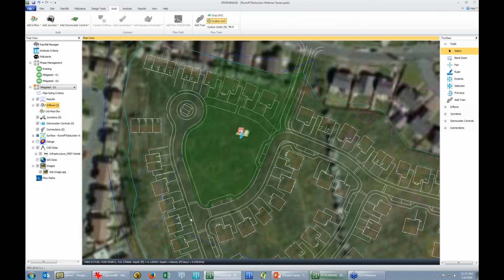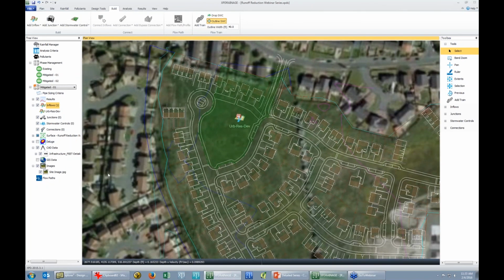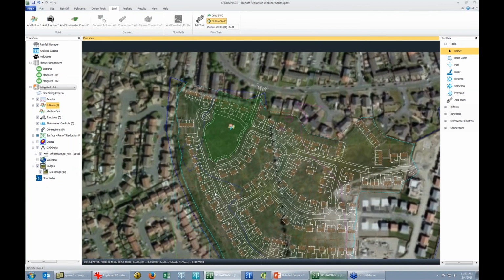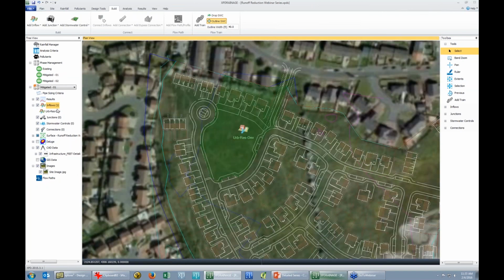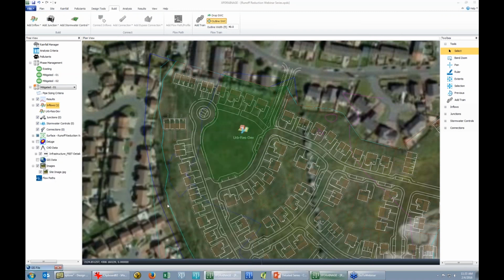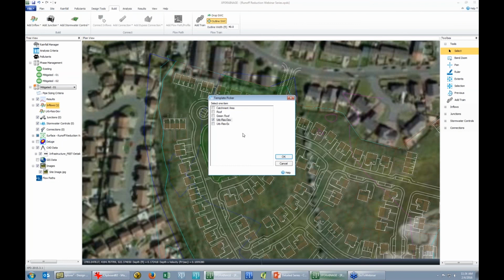Okay. I could continue to delineate further. I could also import, just for the sake of time. I'll show another way to do this. So we could delineate our site, click around, that's 5 or 6 minutes to add those other catchments. Well, what if I was to right-click on inflows, and then I could load from GIS. So I have a shapefile of really the remaining catchments, which were already delineated. Pretty often, this might already exist on a project. Maybe there's a retrofit you're doing. Maybe this work is just already done. It's really easy to do in GIS for someone. Maybe there's a GIS technician. So that's why we accommodate this. You don't have to do everything in our interface. I think it's quite easy. But great, you have someone that did this in either CAD or GIS. We can now import that.